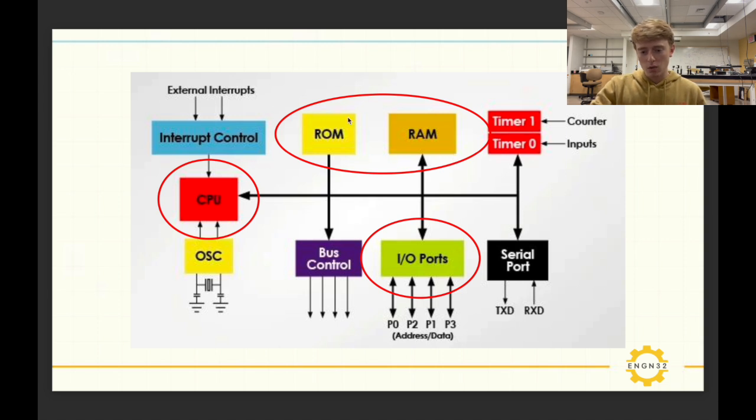Okay? All right, ROM and RAM. So ROM is read-only memory. So this is something that your CPU is going to read one time. It's basically the list of instructions that your CPU is going to execute, okay? So in the case of an Arduino, what we do is we program the Arduino from like your MacBook, your laptop, right? You send it something when you press run. What happens is that code goes to an electronically erasable ROM, so a special type of ROM that can be erased, and that becomes the instructions for your code.